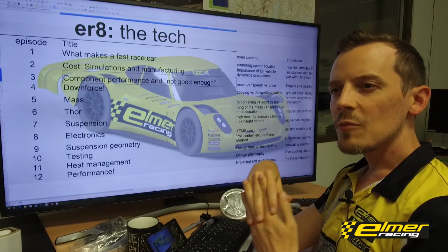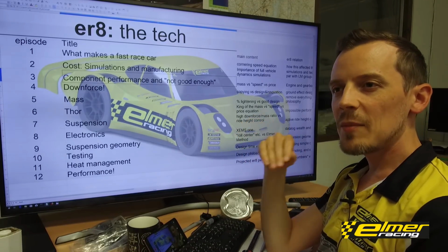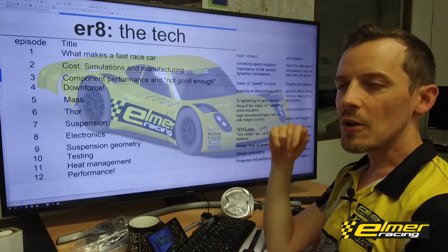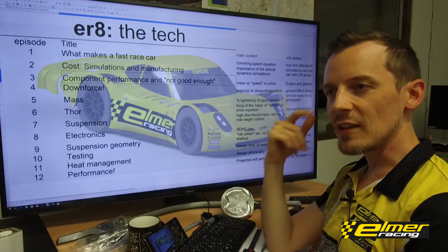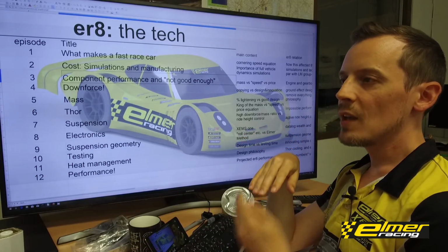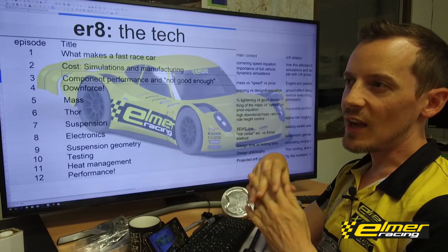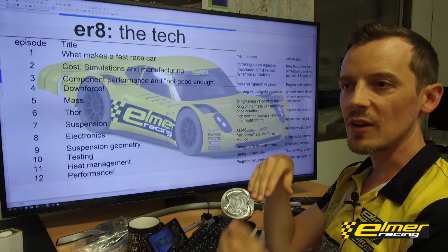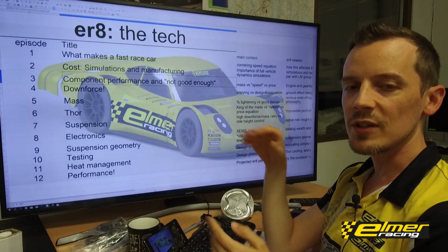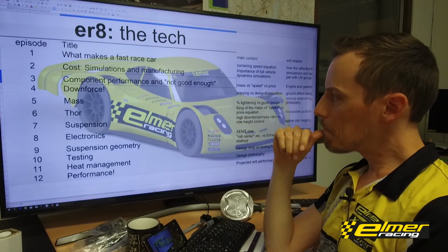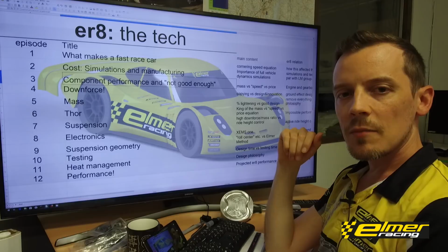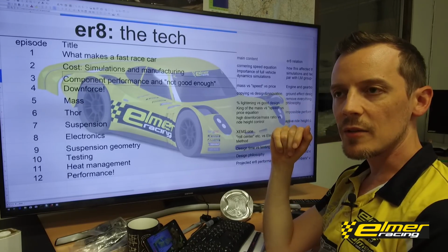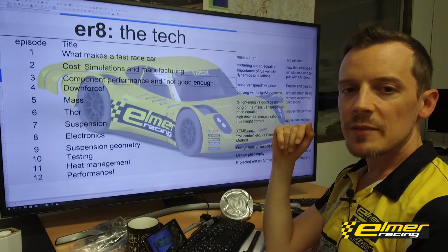So we started looking at that, and could we maybe get away with actually only using 3 gears, and would this suit the car or not? And we started looking a little bit into the engine power band and how much anti-lag we would potentially need to be able to run a very wide RPM spread between the different gears. And we got some numbers from our engine simulation stuff, and on paper it seemed maybe doable.